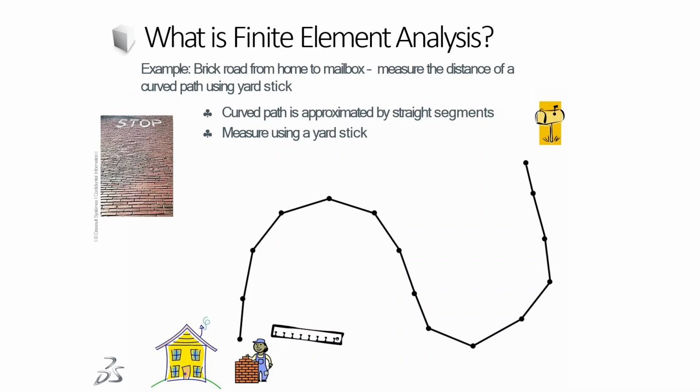Each of those bricks is a very regular shape that you can interrogate and understand the properties of. When you put them all together, it allows you to effectively break down complex geometry into very regular shapes that you can perform equilibrium Stokes equations on, or heat transfer equations, Fourier equations. So it really depends on the geometry, how complex it is, and that will dictate how many of these little elements you need to properly discretize the geometry.